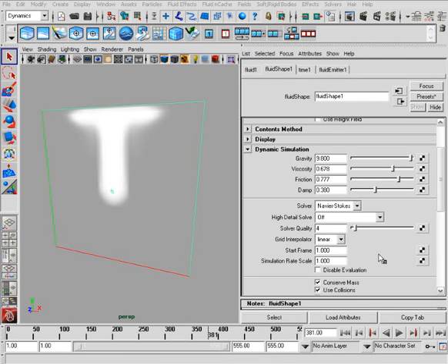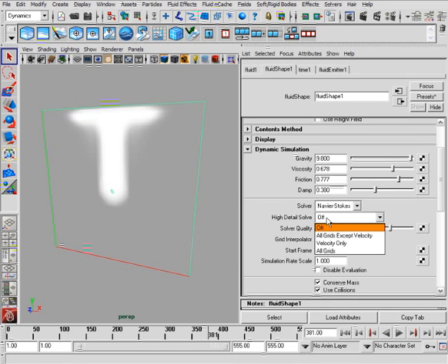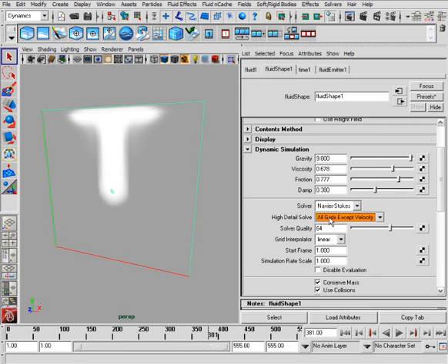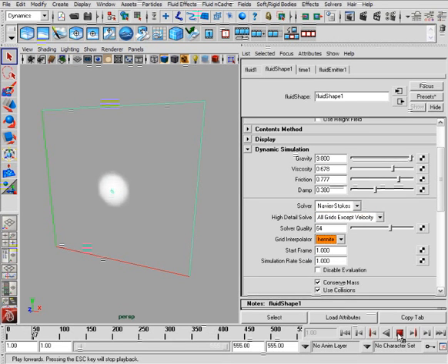Now, if you want the ultimate in high quality, let's set the solver quality high. We would set this to the high quality or high detail solve. I'd go ahead and turn on any of the grids, so we'll just calculate the density, so all grids except velocity, and I would change my grid interpolator from linear, which is essentially a straight line, to Hermite. And what this is going to do is really give me the formula for a very, very accurate simulation. Again, much slower, but the quality is going to be higher.